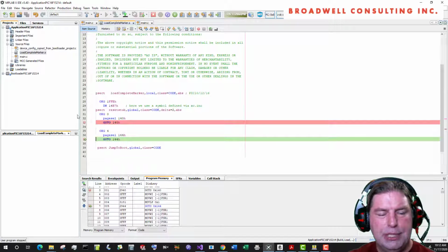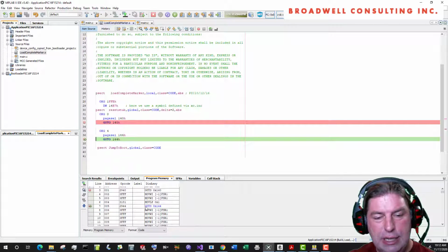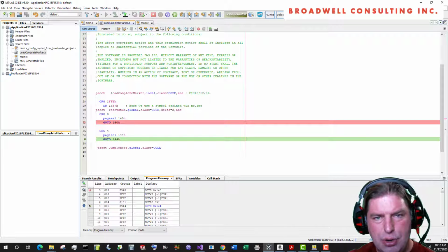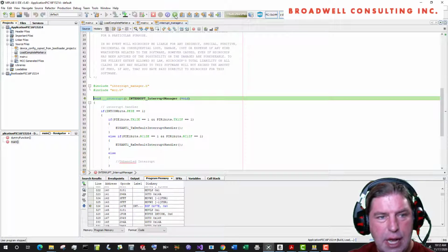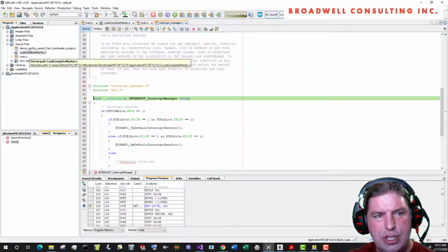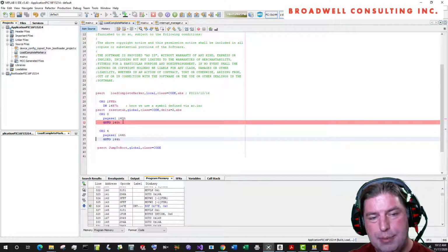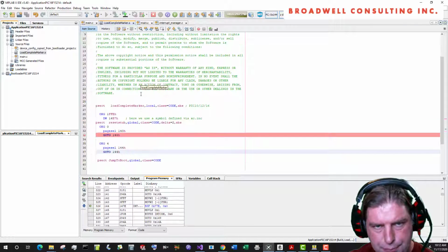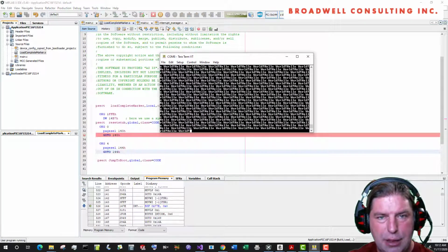the first time we hit an interrupt, it comes down here at location 4, which normally is where the vector or the interrupt handler itself is located. But in this case, we have a go-to. This matches the one that's in the bootloader. And so it jumps up here, and we do get to the proper interrupt space. So that's very good. Again, if you change the location of your application's top due to changing the bootloader or changing the optimization, you'll have to change these values to match whatever is in the bootloader. So we hit go, and everything works great. We're dumping out hello world.